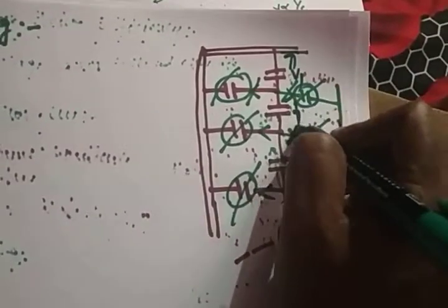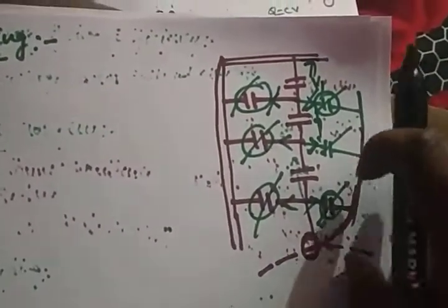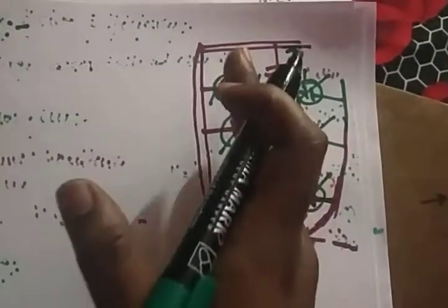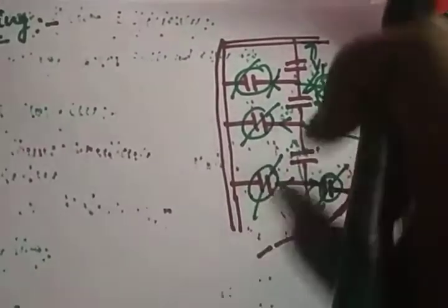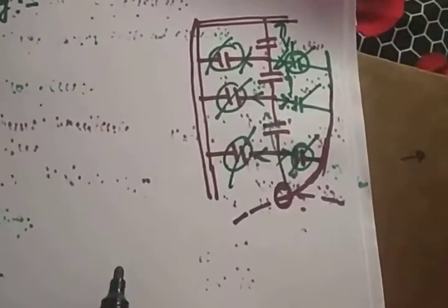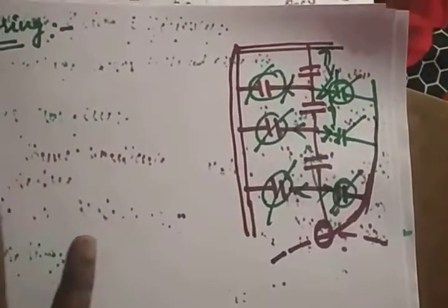So the voltage across each disc is equal, because you are removing the shunt capacitance by providing one metallic ring, which we call a guard ring. This shunt capacitance is cancelled out with the help of the capacitance present at the guard ring, right? In this way we can maintain the voltage uniformly at each and every disc. So we are providing uniform voltage across each disc. That means you are increasing the string efficiency, right?